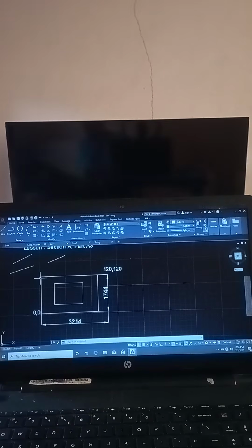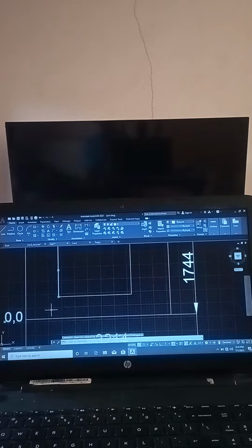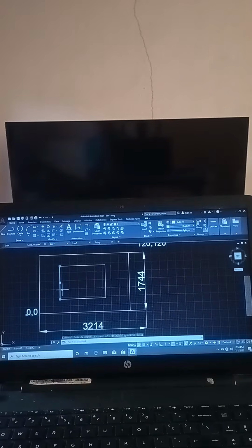The first one is simple window. I go from left to right. Watch what happened now. When you come to simple window selection, going from left to right, whatever you're able to cover will be selected. But the one that you only touch, which is not covered, will not be selected. Take for instance this zero here. They were selected because they were properly covered. Now, this line here is selected, but this one is not selected, and this one is not selected.